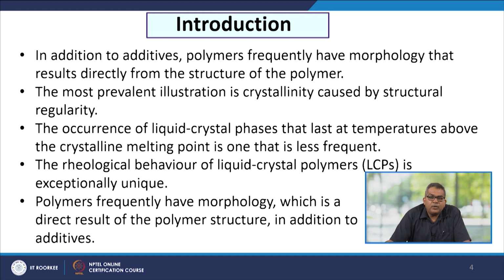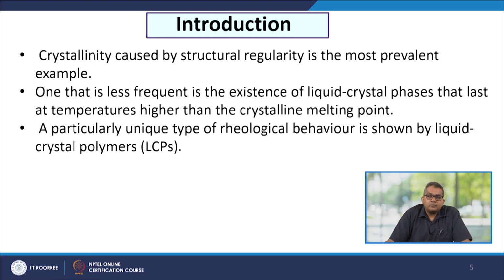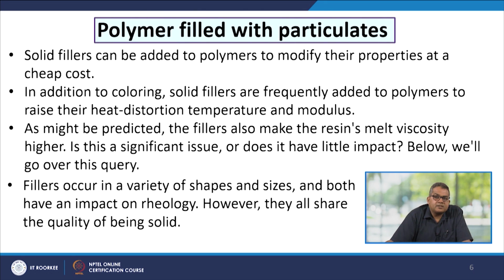Polymers frequently have a morphology which is the direct result of the polymer structure, in addition to additives. Crystallinity is caused by structural regularity. This is the most prevalent example. One that is less frequent is the existence of liquid crystal phases that last at temperatures higher than the crystalline melting point. A particularly unique type of rheological behavior is shown by the liquid crystal polymers or LCPs.